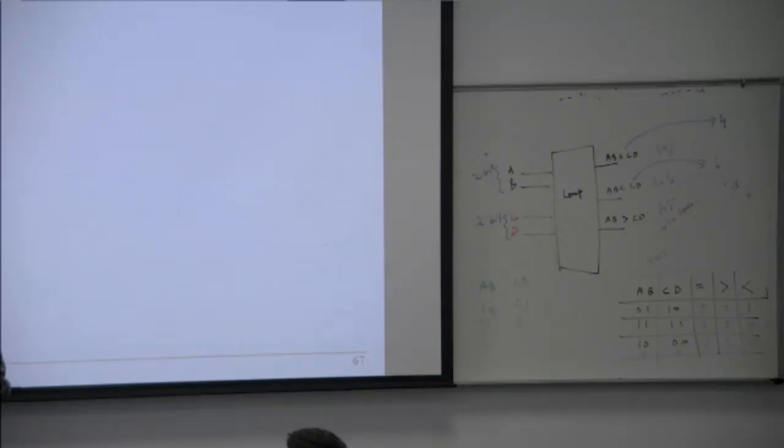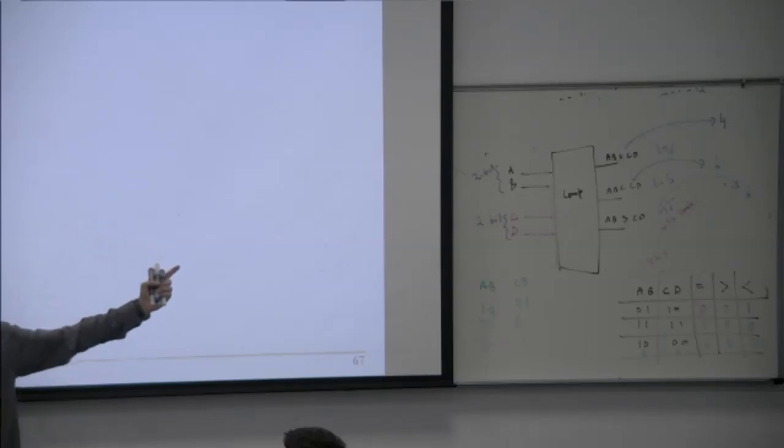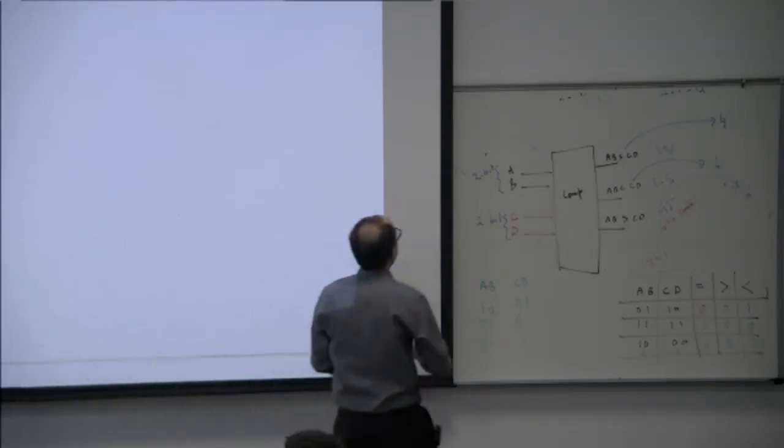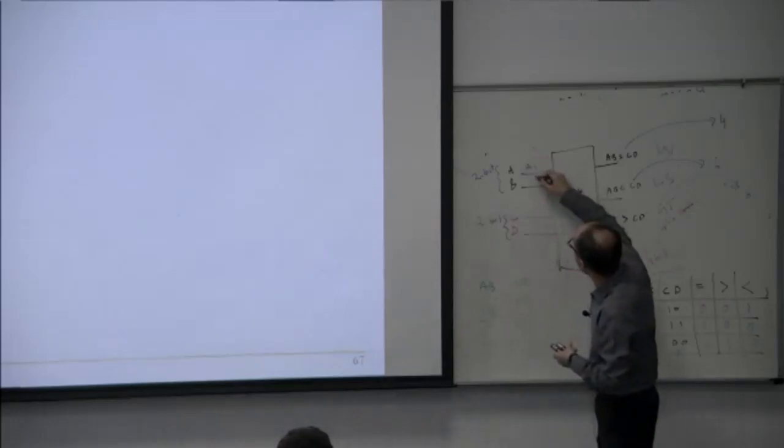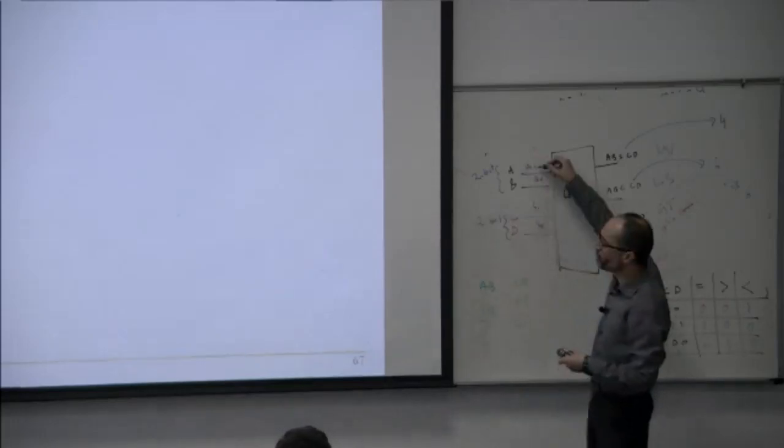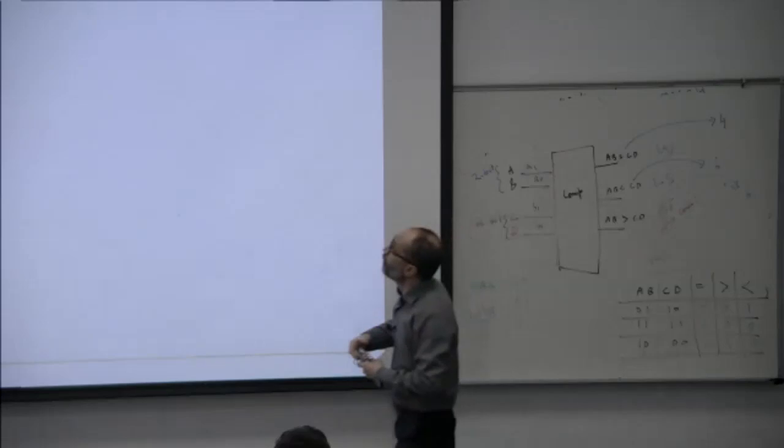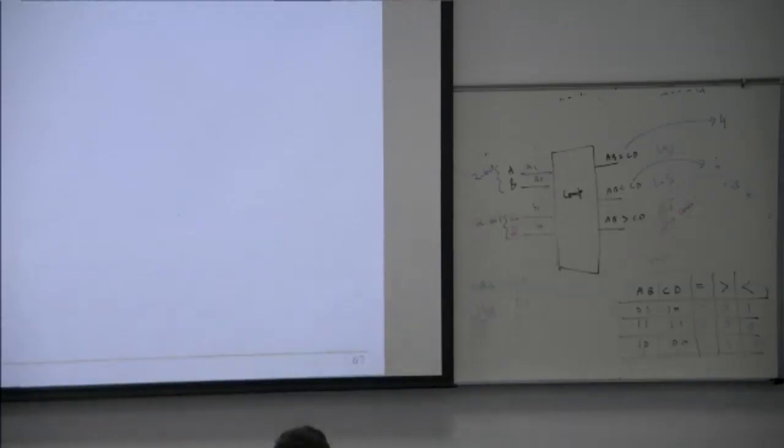Okay. Now we also want to do another description. Now we want to compare two bits, a 2-bit comparator. We are comparing 2-bit quantities, which maybe we call A1 and A0 and then B1 and B0. We are comparing A and B. Okay. Now we have another description, another problem. Now we want to have a don't care, which really means I don't care.